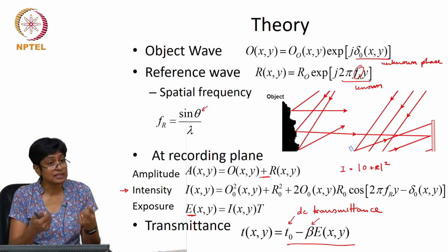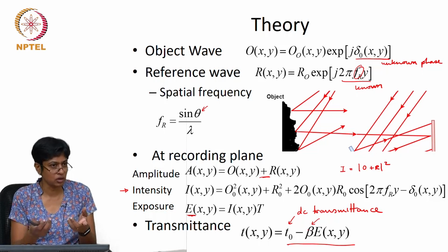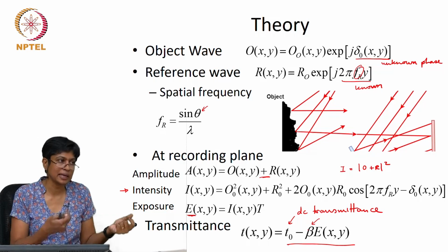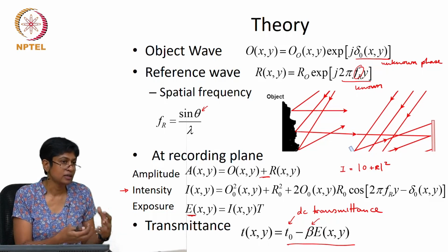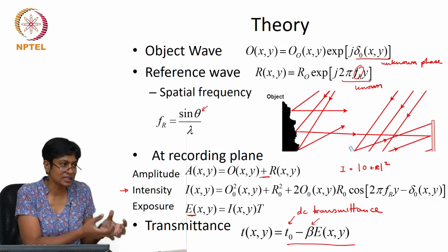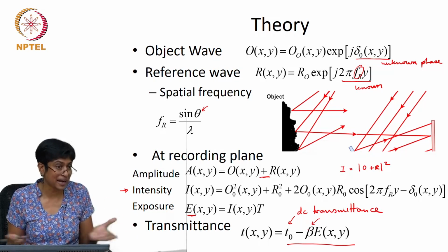This plate has to be, it's very similar to the old film technology. So, it responds to light, that is the exposure part, then you actually have to put it into a chemical and develop it, so that regions where the light fell, you fix that and you remove other regions, and then you are left with this pattern on the thing.